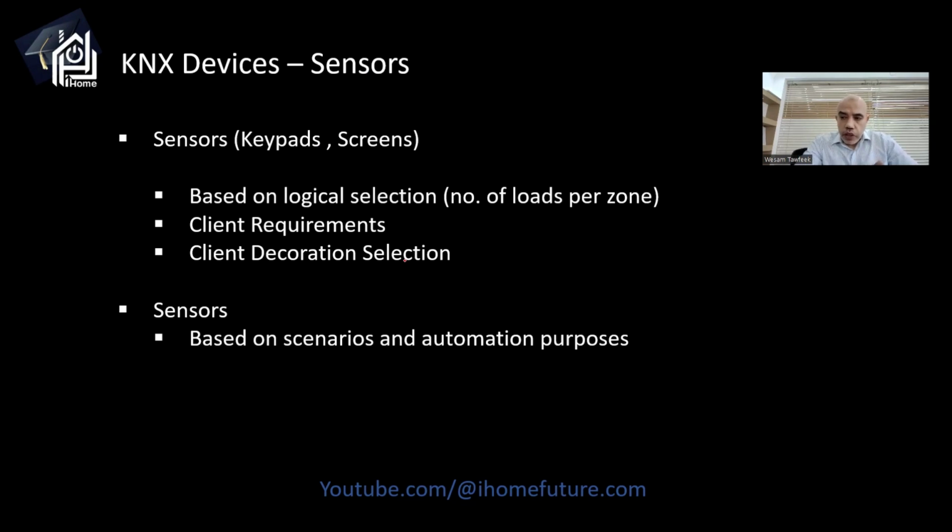So I sit with the end user and I start talking about the logic. Do you need one button to control the lights, or do you need one button to control some other lights? Depending on that, I can get the number of buttons in the house, in the room, or in the keypad, or maybe I can use a touch screen. So I need to sit with the user and find out about that.